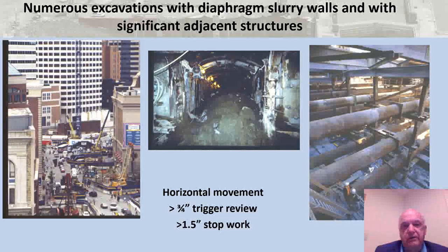A lot of diaphragm slurry walls were put in here with them tied back or braced with some pretty massive crosslot struts.